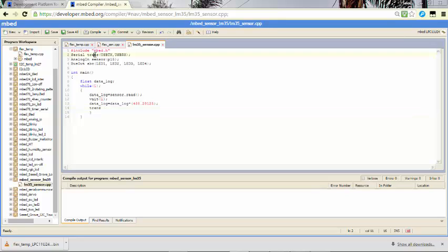So for serial communication I have a pseudonym which defines my board pin. So I write my pseudonym here into that command, and what I will print is my sensor value, suppose percentage f. Let me give a new line every time, it will be easier for me to understand. And what I want to print is that data log variable.